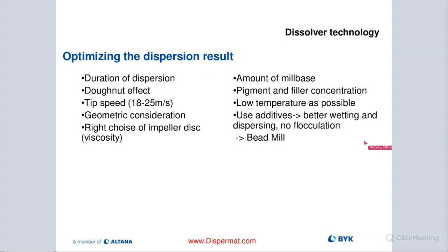Pigment and filler concentration, obviously formulation related. When we are pre-dispersing, it's not as critical as when we are milling, but we do put in quite a bit of energy. So you would see a rise in temperature. So it's probably critical that you have vessels that are jacketed that allow you to maintain a certain temperature. We try to be on the lower end, especially when we're running with solvent products, to have the ability to really cool our mill base.